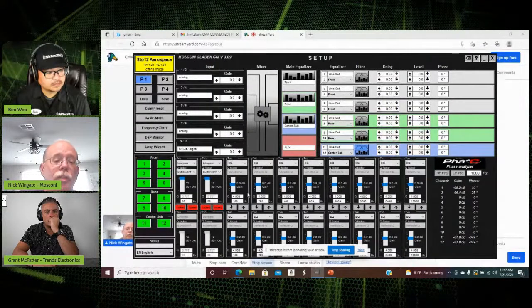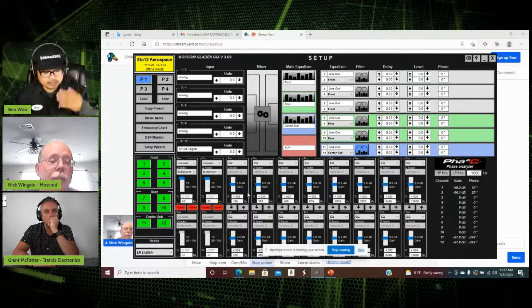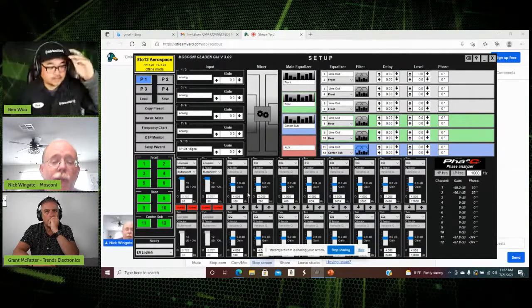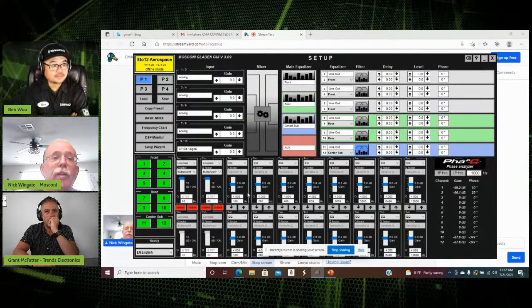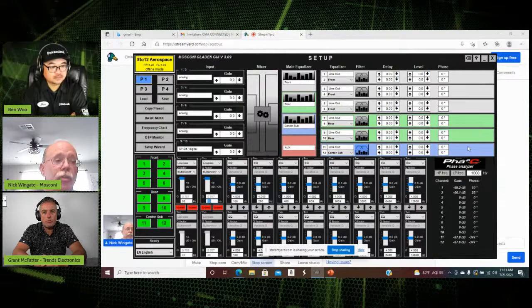Now, from 80 hertz and down, our sub bass is playing. And at this particular point, if we are tuning the car for level output, a lot of times you're going to want to go over to level right here and raise it up, or raise it with the remote volume control. Well, when you do that and you start turning things up, remember, it's not just 80 hertz and down. You're affecting 100 hertz, 120 hertz, 163 hertz, and 200 hertz. And it's going to affect the phase alignment between the mid-bass driver and the sub.